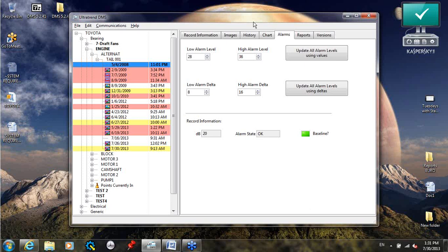So what it does primarily is help us prevent over-greasing or under-greasing the bearing. Even though the manual is telling us to grease it every 2 months with 10 shots of grease, this time around we might only need 2 or 3 shots. The ultrasound is going to tell us exactly how much grease that one particular bearing needs. So using ultrasound, the time base is really the way of the past. Ultrasound is the way to go to help you prevent destroying the bearings yourselves.